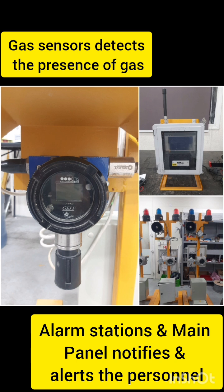How the GDS will function. First, the gas sensors will detect the presence of the harmful gas, and it will communicate to both the alarm station and the display monitor. So alarm station and display monitor will notify and alert the personnel.